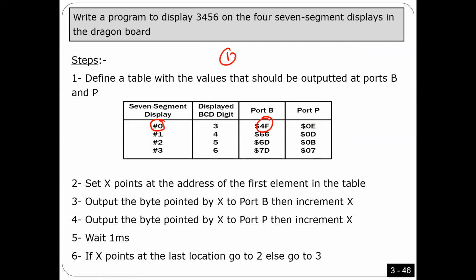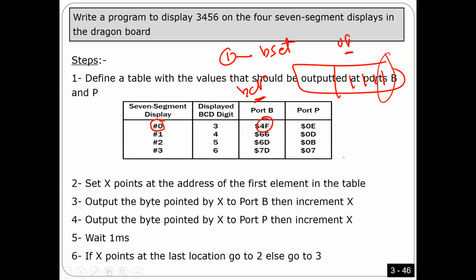The way you have to do it, guys, is number 1, you can use bit set and put here something like 0F, so you can set the first 4 bits. You can set all of them. That's okay. And then you can use bit clear on only one display you want, so you can change one display. For example, you put this one 0, or this one 0, only one, based on which one you want to turn on right now.